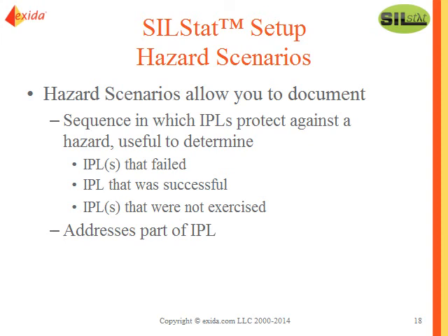So that's the proof test generator. You define a proof test for a specific device, and you can assign those proof tests to the different addresses that these devices are used on. If you modify the proof test, you can apply that to all your devices. So there's basically a central library of these proof tests.